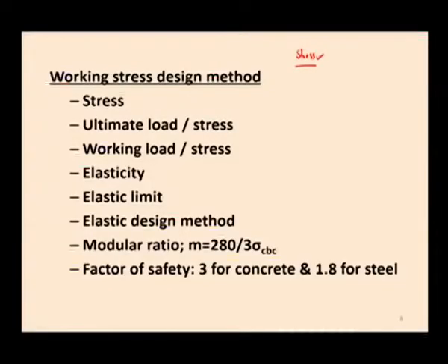When the full resistance to the external force is set up, the deformation stops, or if the body is not able to develop any resistance to the external force, the deformation goes on continuing up to failure. So, the resistance to the deformation per unit area of the body is called stress, and the corresponding change in deformation per unit length of the body is called strain.